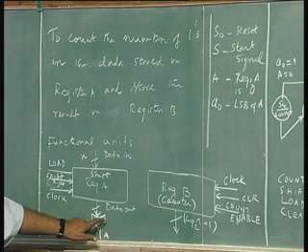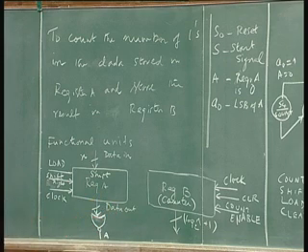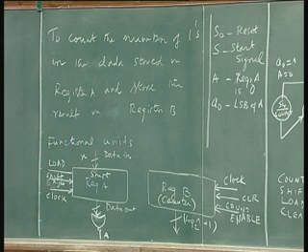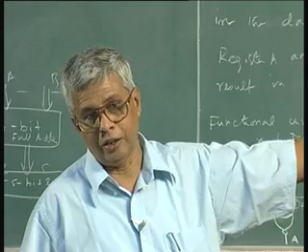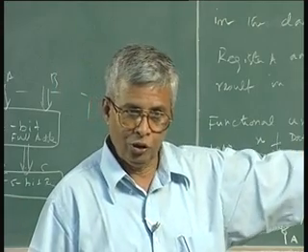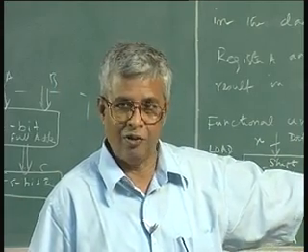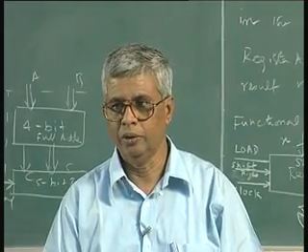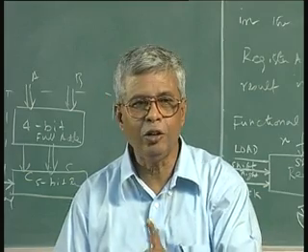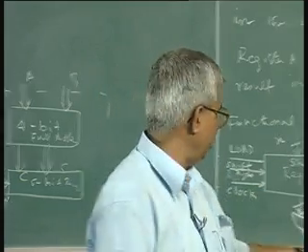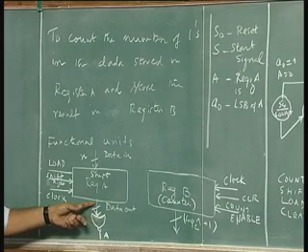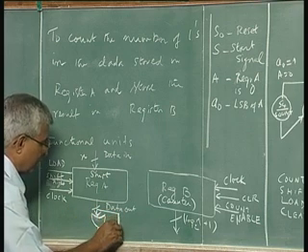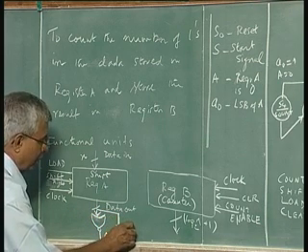This extra functional unit requirement was not evident at the time of drawing the architecture part of the functional unit part. Only when I went to the state graph I found out that something like that is required, at least the way in which I am doing this problem. Of course, you can do it some other way, more efficient, fine. Other thing is, I want to know A0, that is easy, because I have all these bits here. All the 8 bits or n bits are available here, all I have to look at is the LSB. So, LSB is only here. So, A0 is here. So, both of these things come from here.